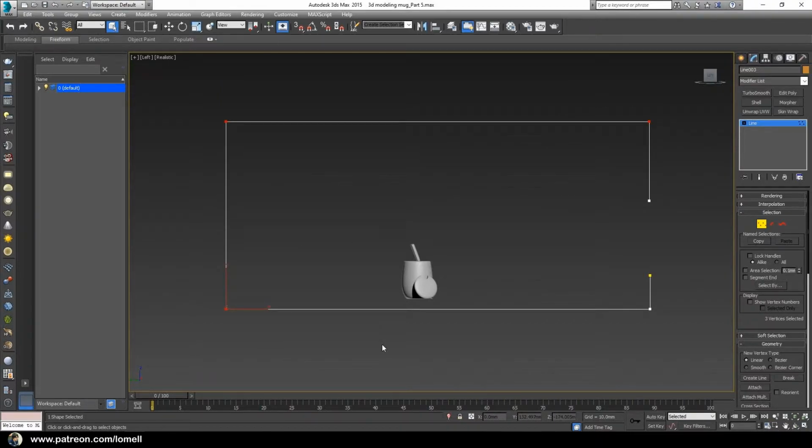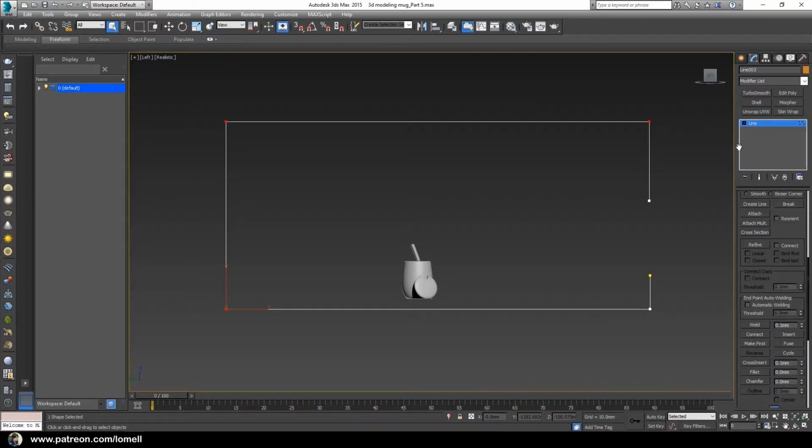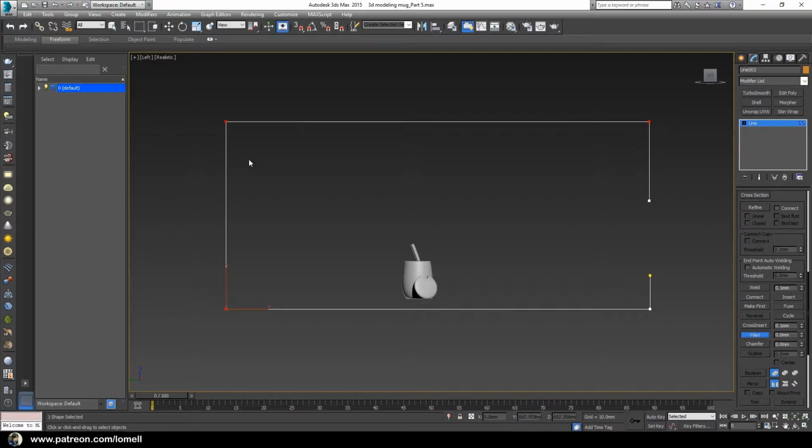Just hold the control key so that you can select multiple vertices, and under the geometry group let's click this fillet button, and using that fillet button try dragging over our selected vertices. Okay, and that should be enough, I think. Release your mouse button and fillet this vertex as well, right? And don't forget to turn off fillet by clicking this one or right click.